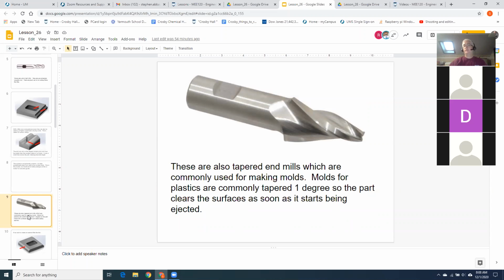Okay, you can also get tapered cutters. So if I were to plunge this thing into a piece of metal, I'm going to get angled faces. And again, this is kind of a mold making tool. I included this in the course because almost every job I've had as an R&D engineer, I always ended up making plastic injection molded something, whether it's medical consumables, aircraft lost wax molds, something. You're going to run into molding a lot if your career is anything like mine was.